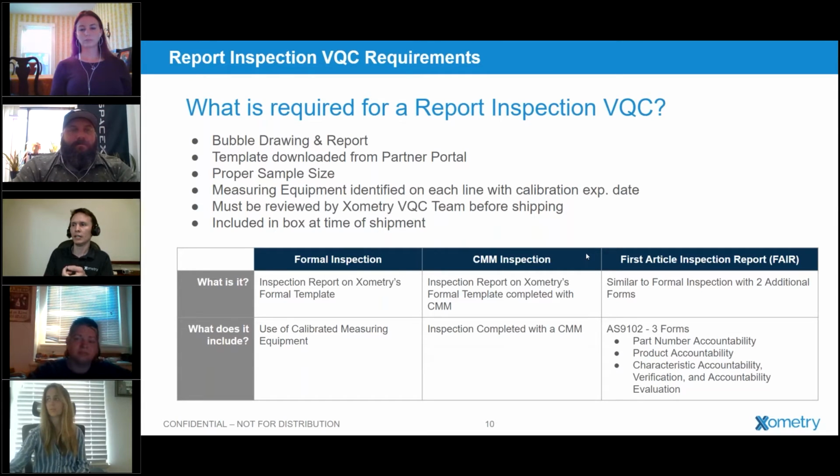As Jason says, it's very important that you're measuring equipment. So if we are saying that this dimension is good and validates this product and it's good for the customer to receive, that equipment must be calibrated. They must have some sort of traceability of the calibration for that equipment and expiration date. And please make sure the equipment is appropriate for measuring the dimension. So don't measure a plus or minus 1/1000th hole with a pair of calipers. It's not appropriate, right?